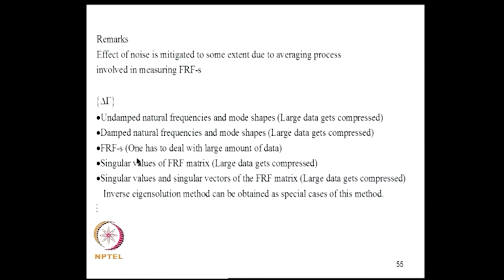But on the other hand, if you are using FRFs, you have to deal with a very large amount of data. Similarly, with singular values of the FRF matrix there is a data compression. Again, if you use singular values and singular vectors of the FRF matrix, there is a compression of large data. Actually, you can show that the inverse eigen solution method will be a special case of this approach. I am not sure if we will be able to get into all the details, but I am pointing out that you can explore that fact by your own methods.